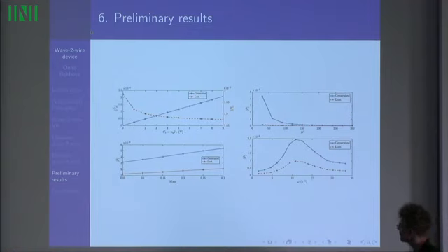Now you would say, well, take infinite mass, but the point is the buoy needs to fit in the contraction and shouldn't hit the bottom, so there is a finite size and finite mass. Otherwise it sinks, and then it doesn't float anymore, which is just a sunken thing, and then it doesn't do anything. And you can look at the power generated and lost as a function of the incoming waves, and then you see that there is a resonant peak.